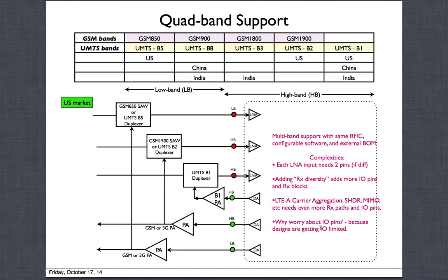One thing I want you to keep in mind as we go on is that I/O pins will become very, very important. I keep stressing this a little bit, but I'll stress it more and more. You can put more and more hardware, and as these input output pins grow, it is actually becoming a problem. Why is it becoming a problem? When you do a design, and as I will show, these systems are very big, massive, complex systems with lots of blocks, right? You might think that these blocks are going to be big enough, and if you put all the blocks together, that determines the total die area.